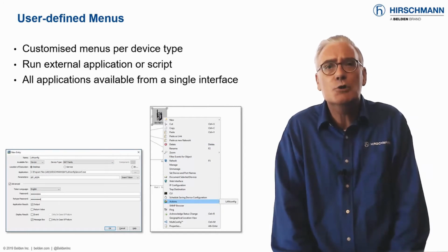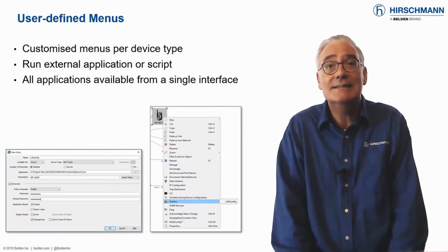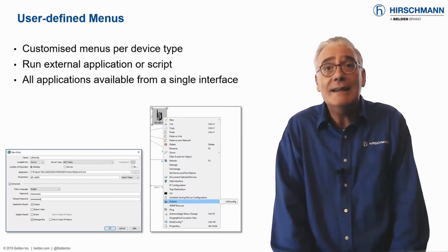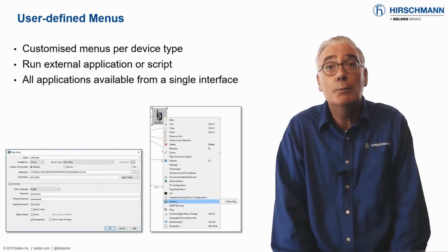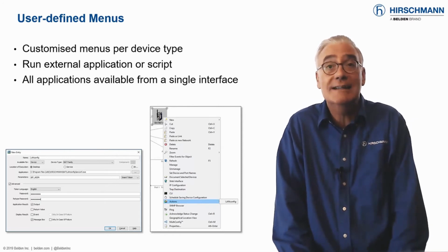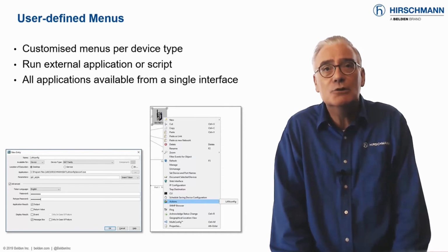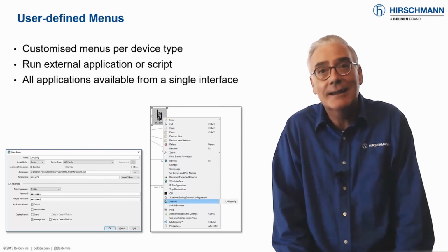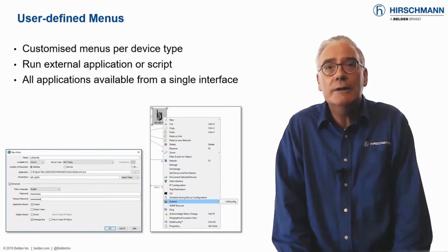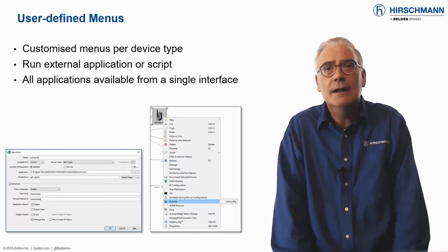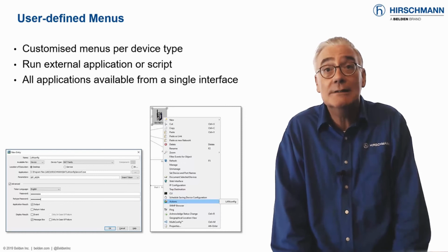Industrial HiVision includes the option to start other device-related interfaces directly from within the graphical user interface. For example, right-clicking a switch's icon will allow you to open the device's web interface or a command line like Telnet or SSH. But is it possible to run other applications, especially for third-party devices? Actually, yes. You can design your own device menus and then run any applications you would like. Wildcards are available for parameters such as IP addresses. It's even possible to include passwords in the command line.